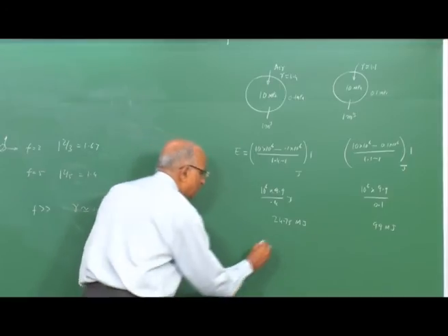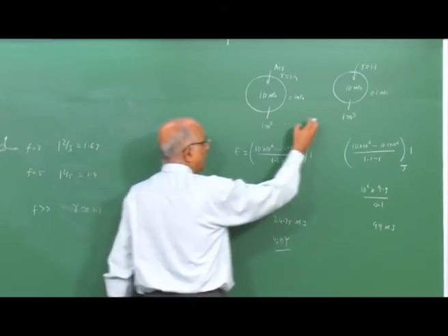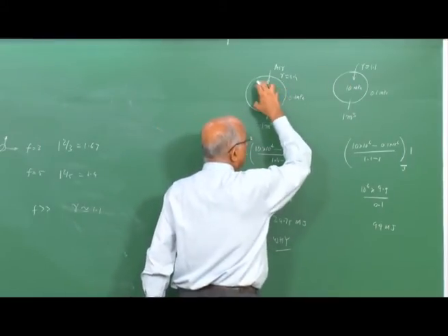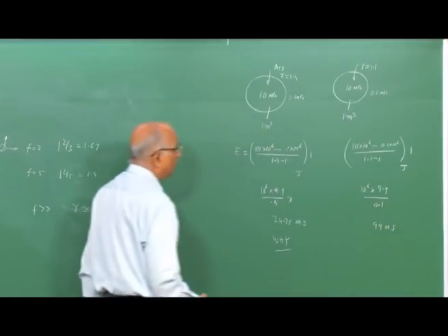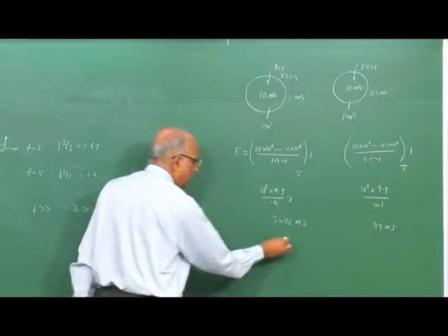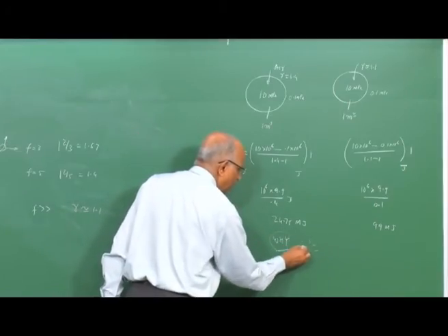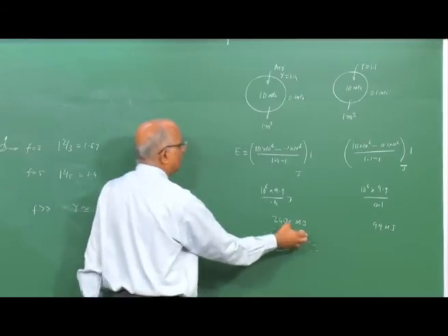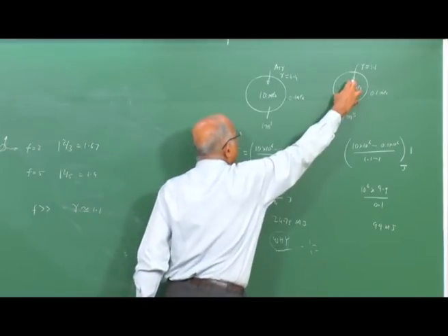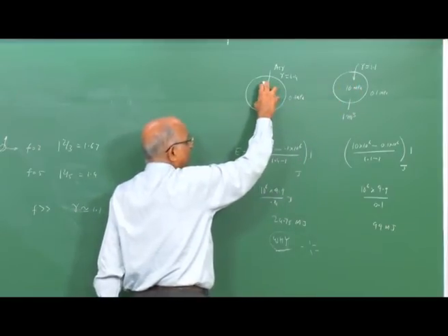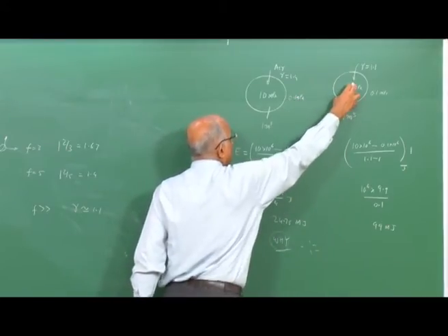The question is, why should this happen? Why should an explosion of the gas at the same pressure, same initial conditions, same volume and same ambient conditions release much more energy? The thing is that a more complex gas, because of its different modes, different degrees of freedom, because of its structure, can hold much more internal energy. That means the initial internal energy of this gas is very much higher than the internal energy of this gas. And since we are talking of the drop in internal energy, the complex gas gives me much more energy.